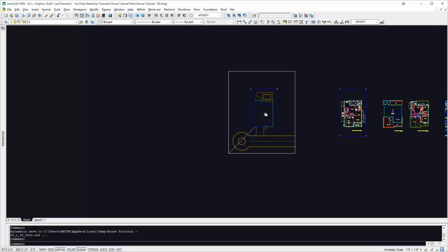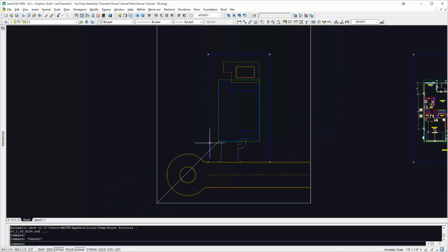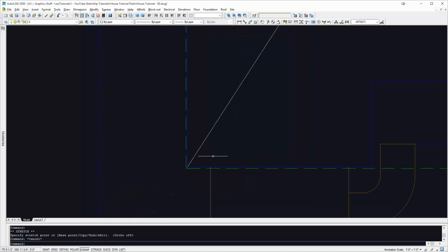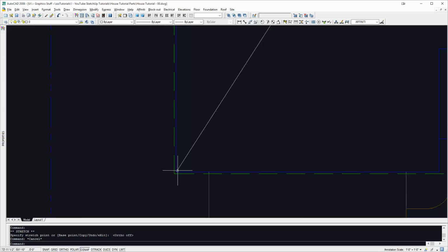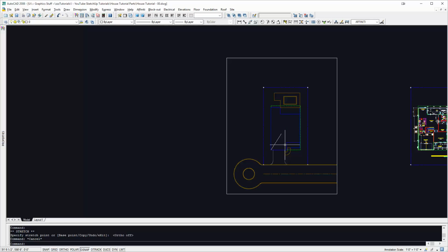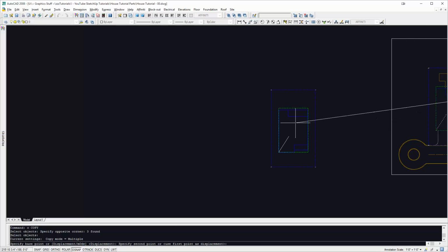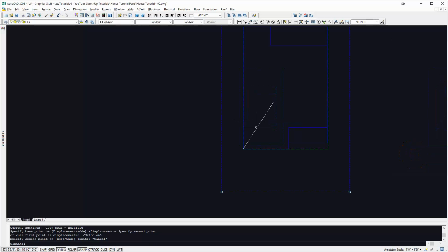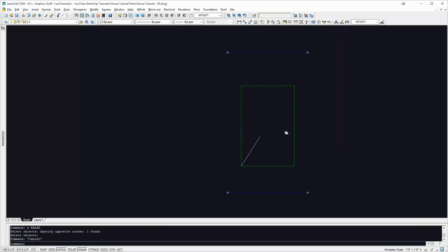So again, let's go back to our AutoCAD file, and I'm going to grab this same reference point line because we're still at the corner of our house, because that's just a great place to use as a reference. And this time I'm going to copy my sight lines along with this reference. We can get rid of the house outline, we don't need it.